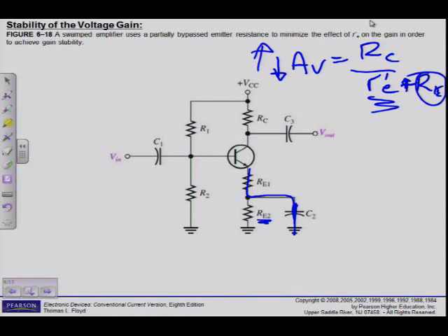I want to increase my voltage gain, so I'm splitting the value of RE into two. So I have now RE1 also in my formula there, which is now only 500 ohms and not 1000 ohms anymore, and I get a bit more voltage gain. Now I've got a stable circuit and I have increased my voltage gain a bit. Alright, that is why we do swamping.